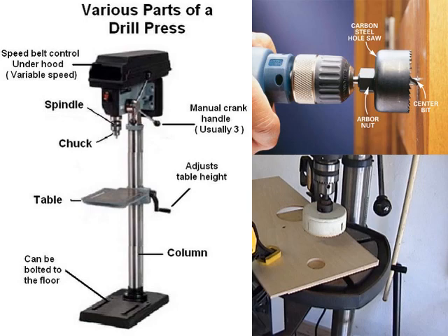You've got your spindle and your chuck. You put the drill bit in it, and then you turn it on after you've set your speed, and then it has the little metal crank there that you turn, pulling it towards you, and it pulls the whole top down, or some are designed to pull the table up. But it brings the drill down to the thing you're trying to drill in, and it drills the hole.